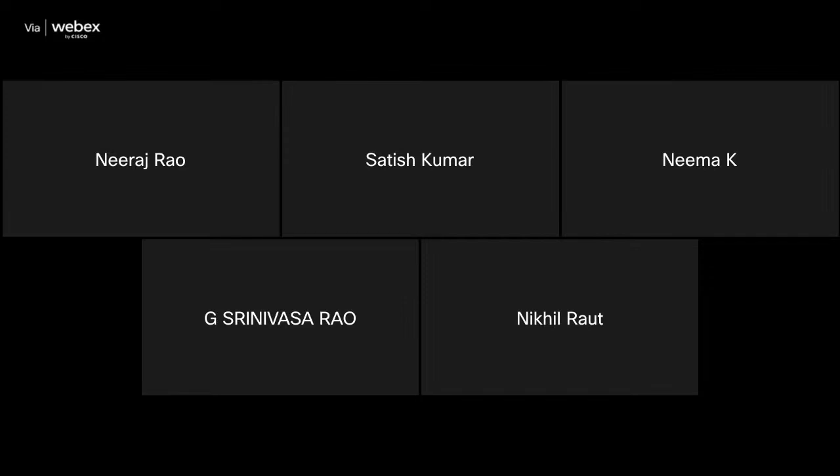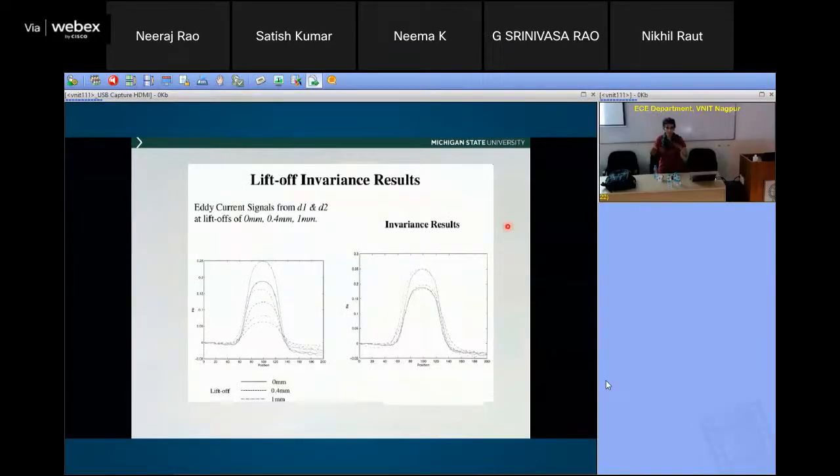So what I show on this plot, there are two defects, okay? And three liftoff variations. And you can see everything sort of overlaps. This may be a small defect, large liftoff, large liftoff, large defect, and you can have a small defect, small liftoff. So unless you get rid of the variability due to liftoff, you cannot really interpret or classify it as a particular defect D1 or D2.